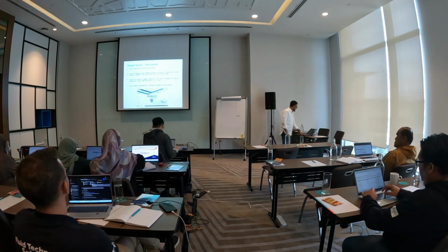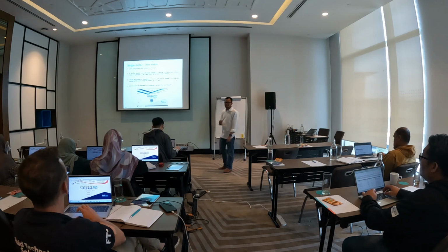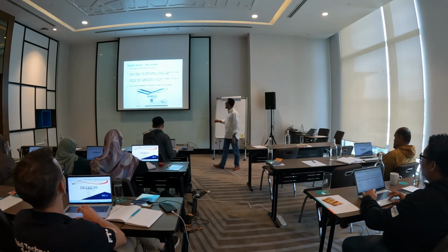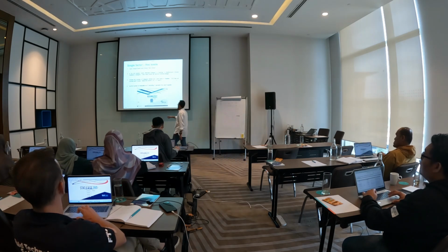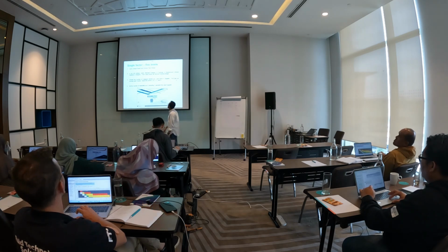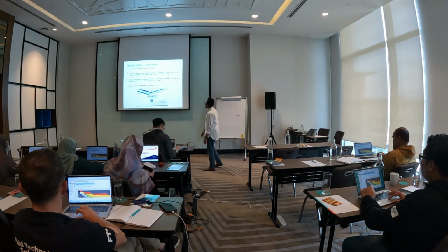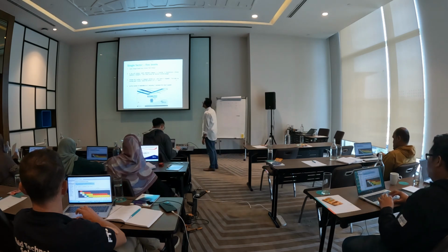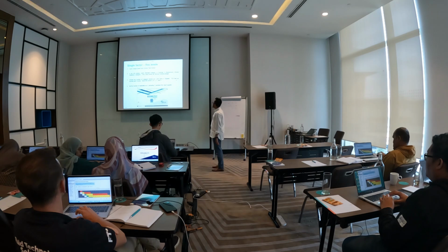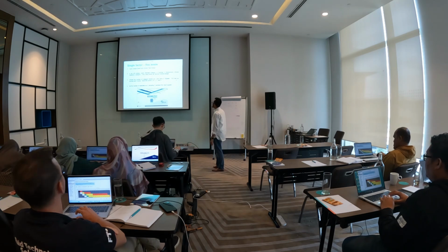Okay, you can open Design Expert, and maybe you can follow step by step. In the sidebar, you can click New Design. I think this one is on version 12. Then in the sidebar, choose Standard Design, Factorial, Randomize. Choose multi-level category.